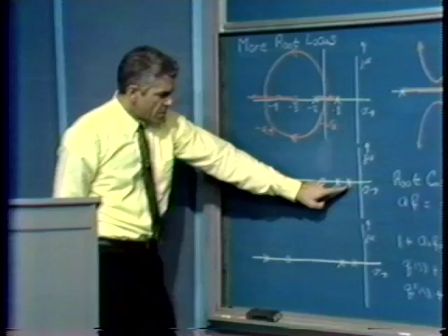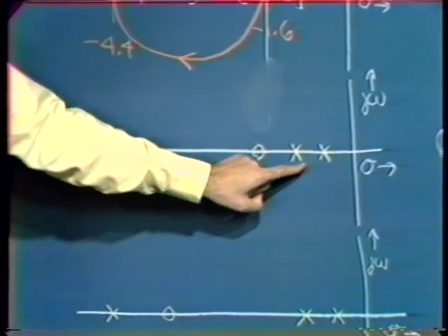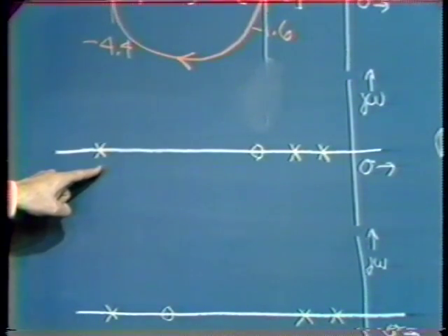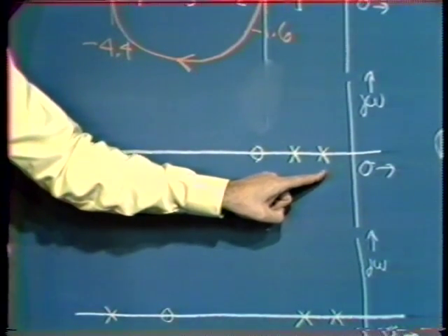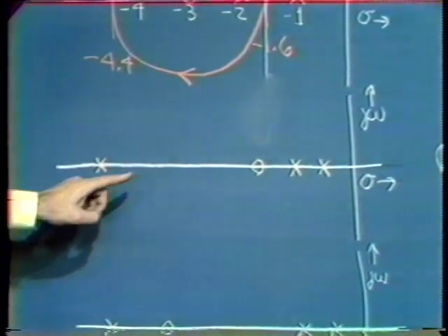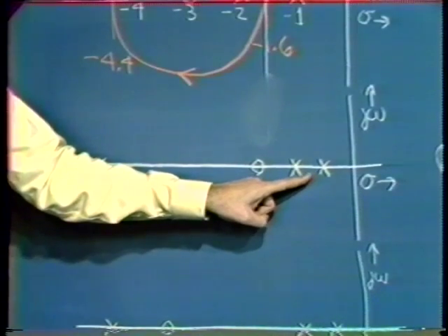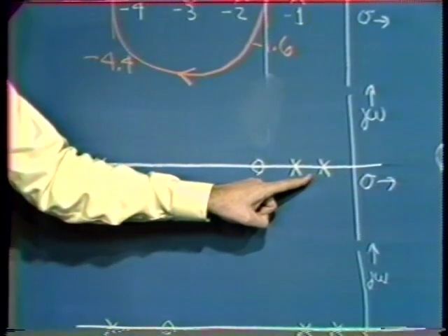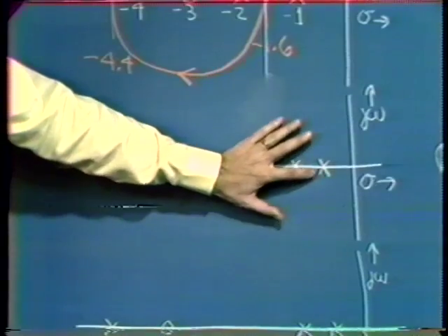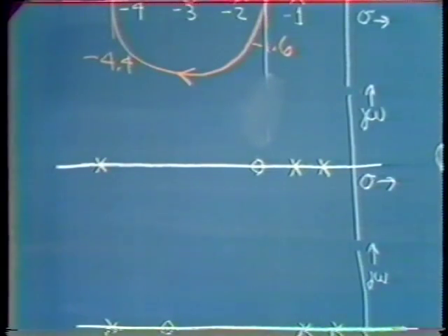Here I've shown another one where we assume we start with 3 real axis poles. Again, we did a calculation concerning this last time, and the numbers, of course, are dependent on the exact locations of the real axis poles, but we did a calculation where we had one pole at -1, one at -2, one at -10, and we found out that we could get very small amounts of desensitivity before we began to run into a stability problem. For example, we found out that the damping ratio of the closed loop pole pair closest to the origin got as low as 0.5 for an A naught, F naught product of only 2.2.